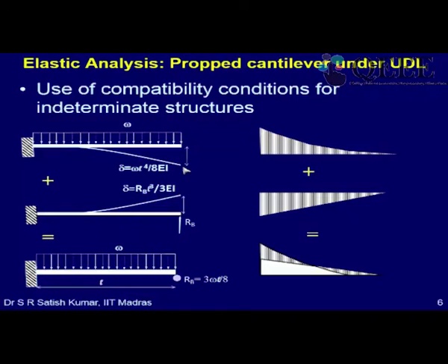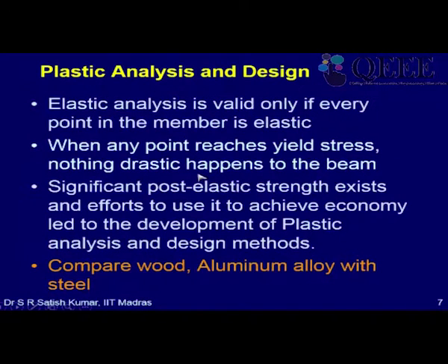So these three are the three pillars of structural analysis. So we use these three sets of equations to solve any problem. Okay, and in the case of elastic problems, we will say that stress is equal to E into epsilon, but that will not be valid once the material is inelastic or it goes beyond the elastic range. So as a consequence, we have to necessarily ensure that the stress for any beam remains within the elastic limit if we want to use elastic analysis. So that becomes a major limitation for this analysis.